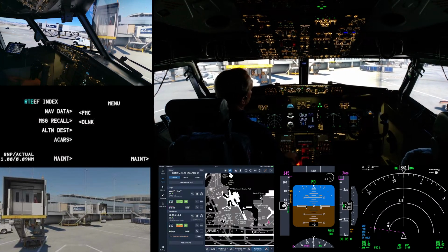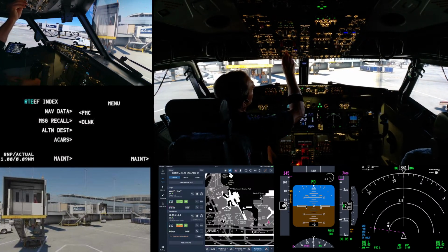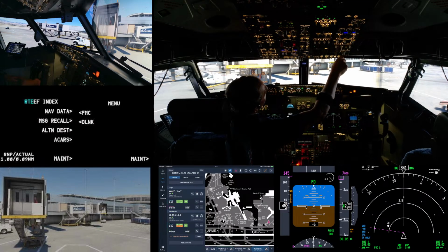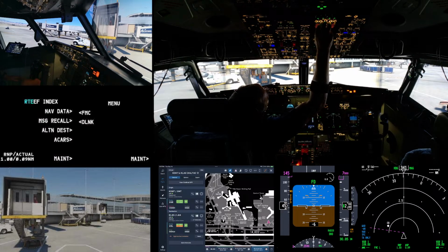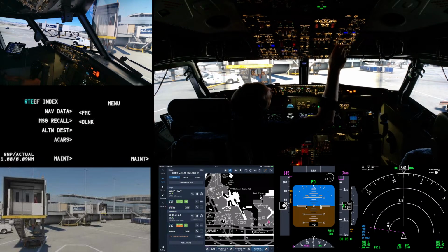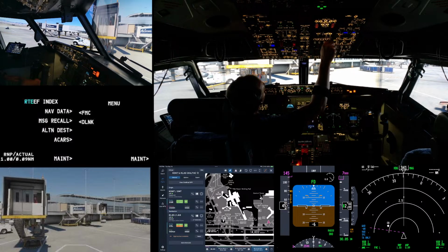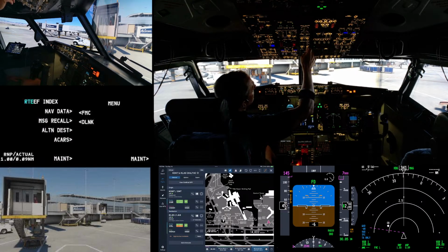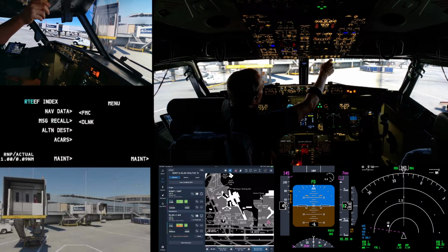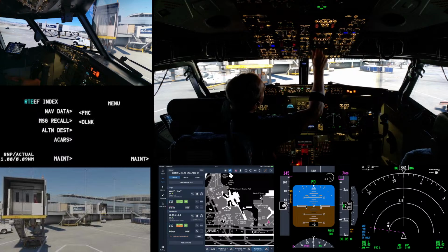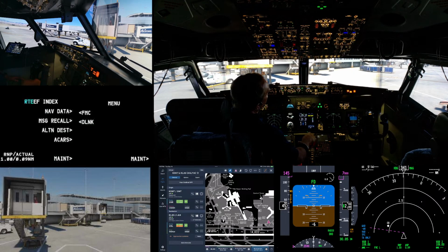All right, so on the bus, APU is good. And we can stop the engines. Fuel cutoff. Window heat off. And we'll release the passengers. Let's go ground power. Leave collision on until we call the ground crew and ask them to get me some juice.